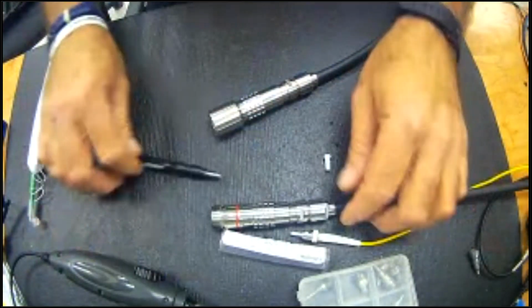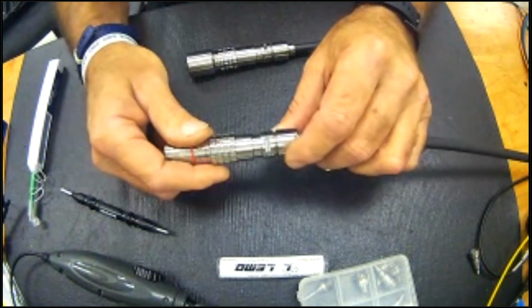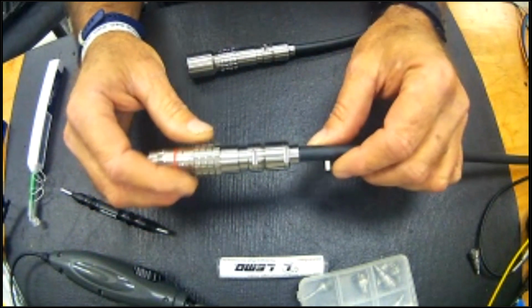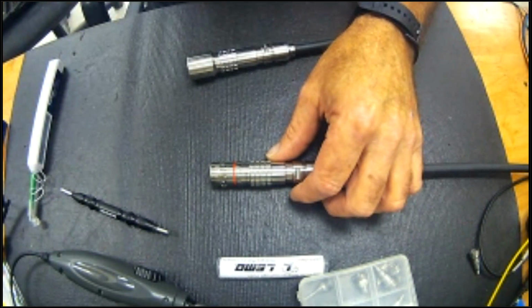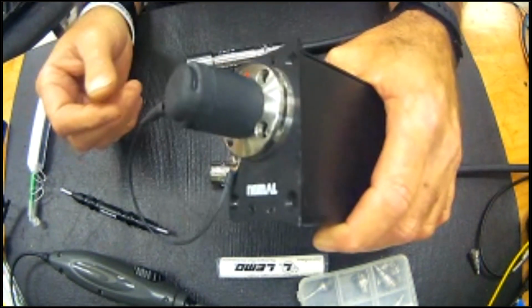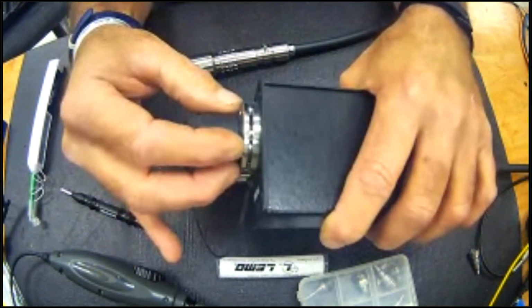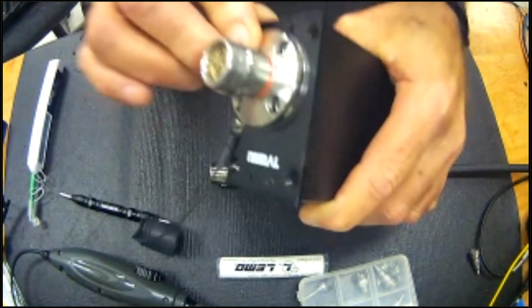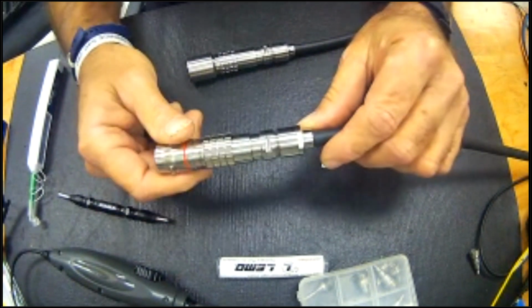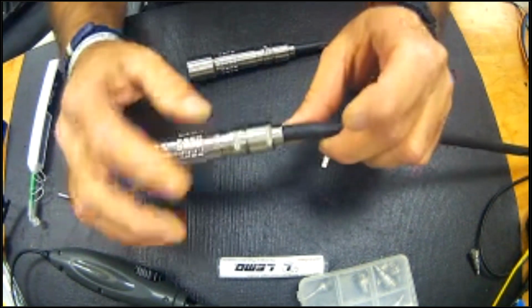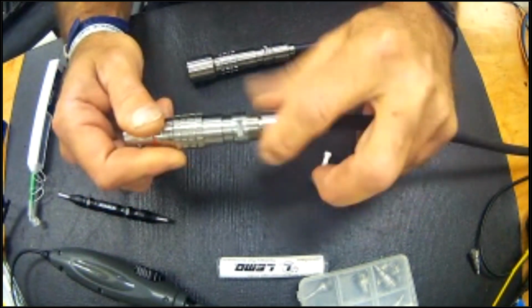I want to quickly show you something unique about the LEMO and the fact that I can also swap heads on this. And a quick breakdown of the connector. If you end up with a patching system where the panel mount connector is mounted inside, it was usually mounted from the front. It is much like the triax connector, cannot be mounted from the rear as it has moving parts. So being able to disassemble this connector and reassemble it without losing the parts is to me very important. There are 3 pieces to this connector. There is a back nut. There's an intermediate male-female body.